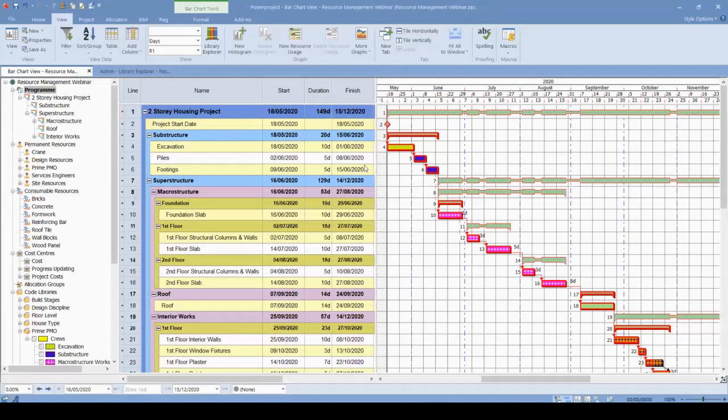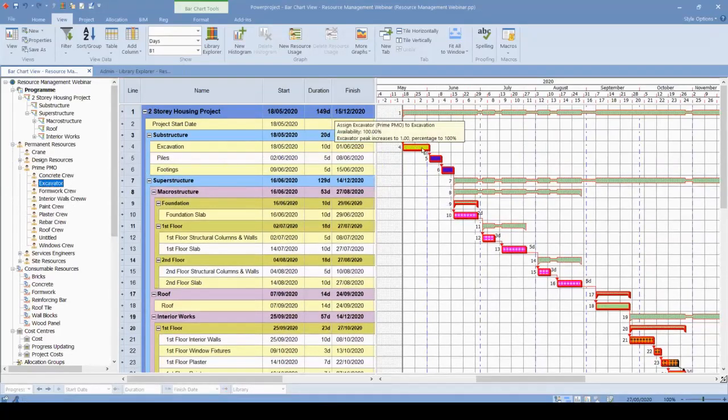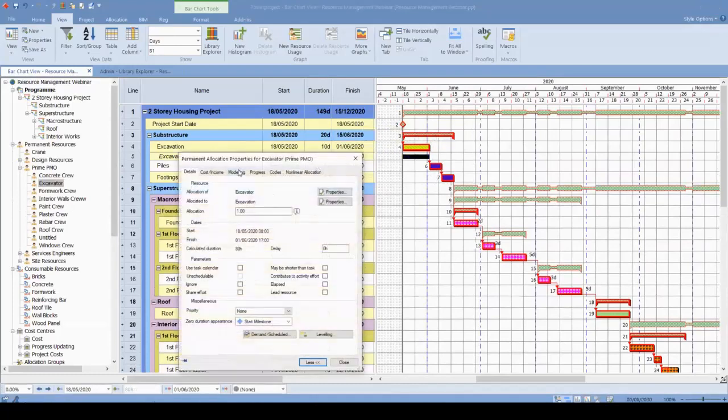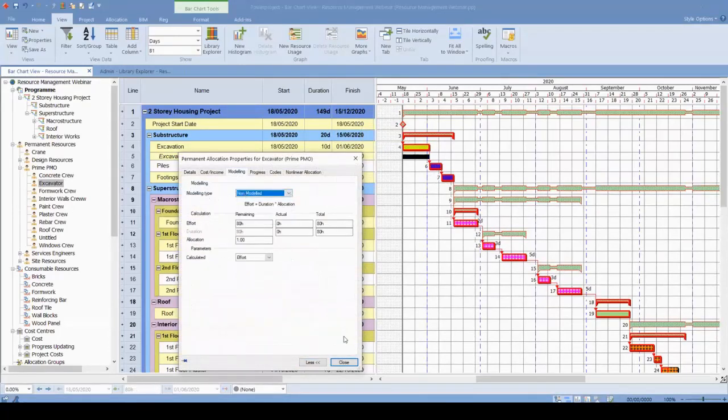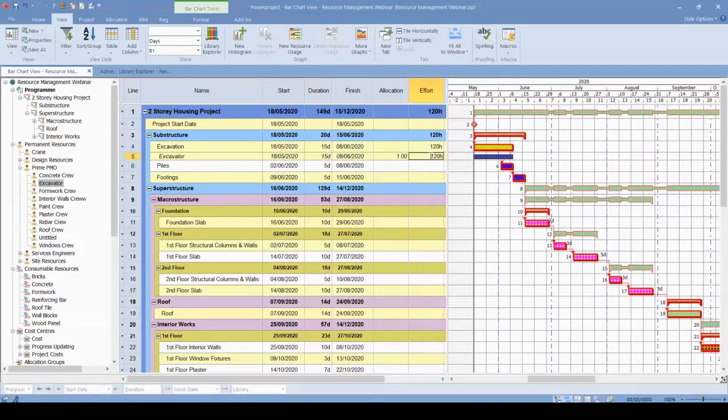So let's go directly to our schedule, and we see our excavation activities here. I want to allocate an excavator here, and by drag and drop I can directly allocate it; let's Control Z, and allocate a resource to our activity. If I'm using the non-modeled modeling type, I know that if this activity increases to 15 days, the excavator will work for 15 days. The effort, which is man hours or machine hours, will be calculated directly, and you can also see that the allocation number is 1.